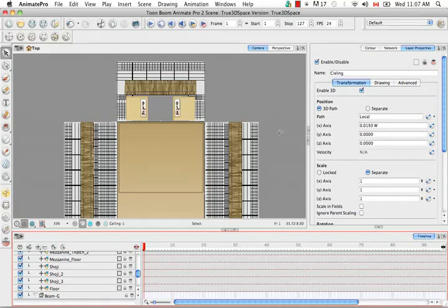Although it's all vector-based and although your file size is quite small for that, it is really hard on your RAM and your video card, because it needs to render as you're rotating in 3D, or it's sort of running the scene. That part of it is difficult, usually, for your computer to handle. So in instances like that, it's actually good to show and hide only the sections that you need. So hide the sections you don't need and show the sections that you do need when you set up your camera and you set up your scene and you're running your actual scene.